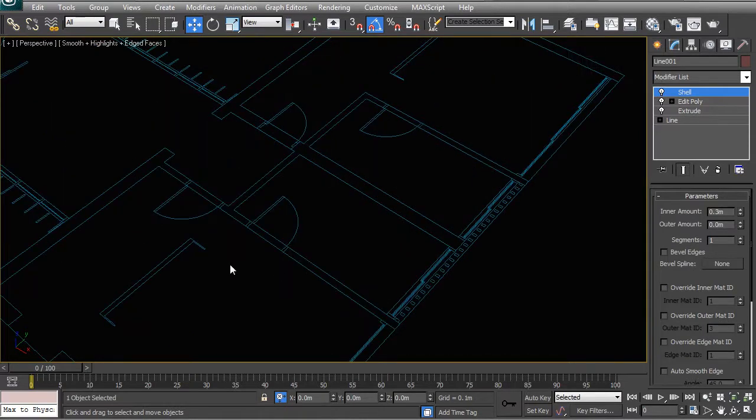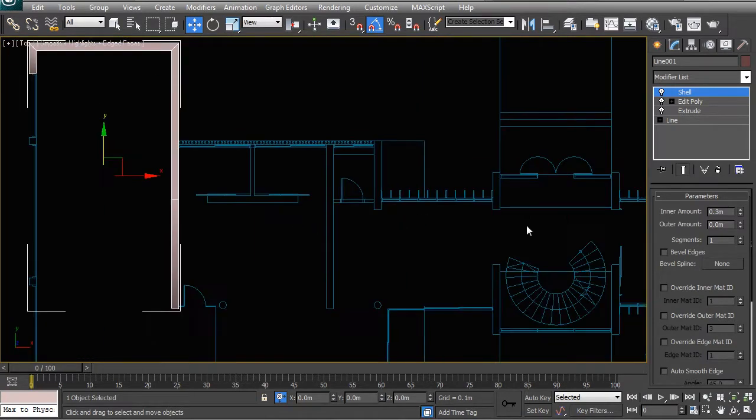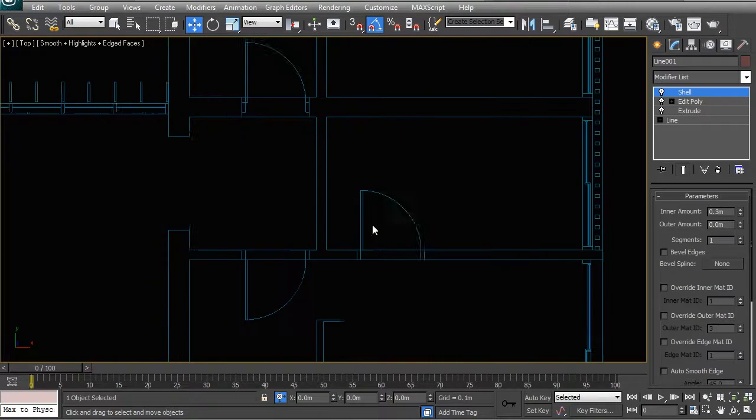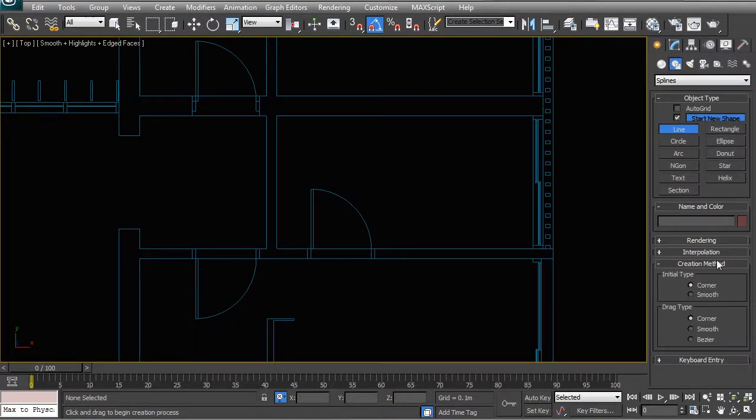So these internal walls are slightly more complex because they are T-shaped. You can't really decide what the inside and outside of it is. So let's now go and start drawing up these walls, and let's just see what we end up with. We start off with the same method that we've done before, but now I'm going to add a vertex at the edge of every door.